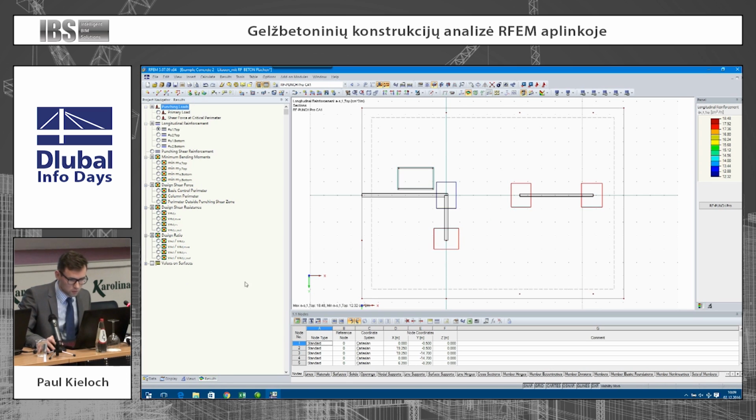So you can check which reinforcement was considered for the punching proof. You can switch through this. In the bottom areas I have added no additional reinforcement, so that is written exactly here in this result panel. And I can also switch, for example, into the design ratios.